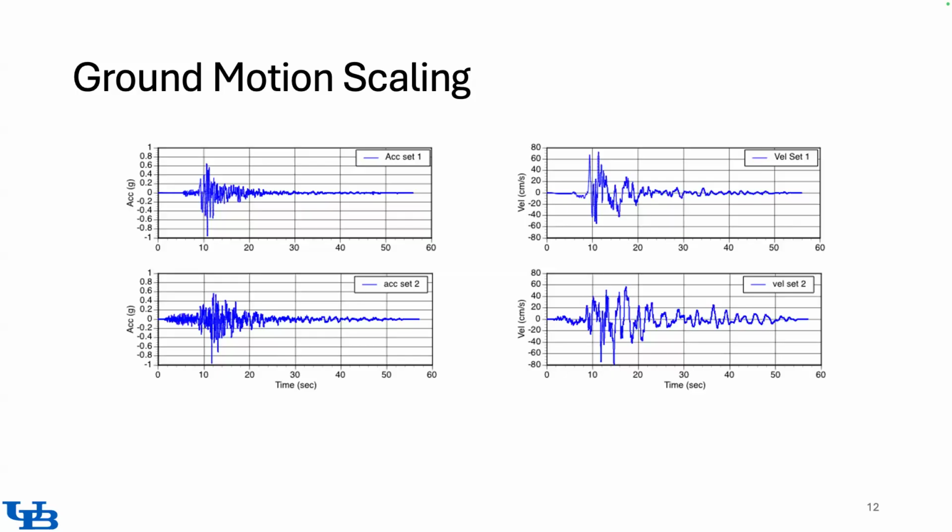So this is the ground motion from an earthquake that is over a larger distance. But other than that, in terms of frequency content, they are actually quite similar. So if features like that matter for a critical structure, then you should try to explicitly account for them, model, and filter the ground motions based on them. But if features like that are irrelevant, then both ground motions will be valid for the structural analysis that you would perform.